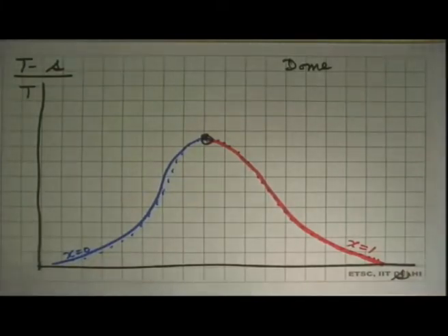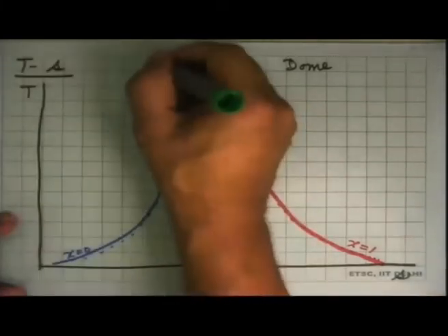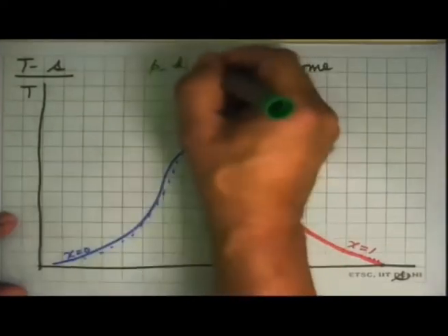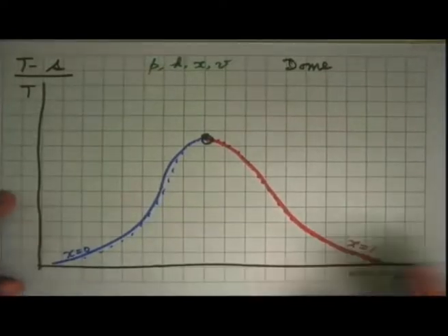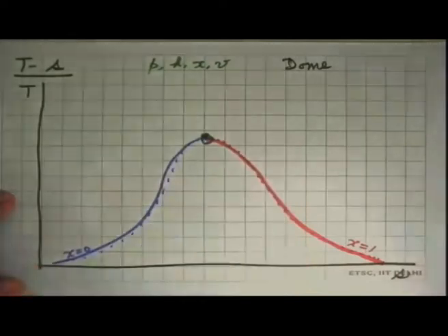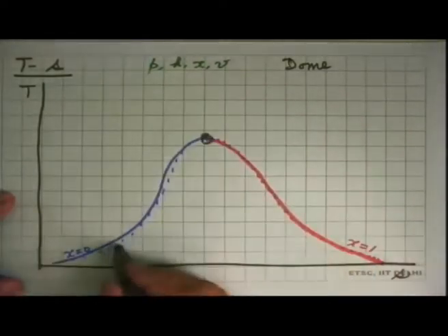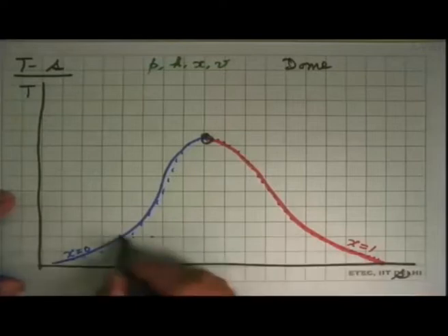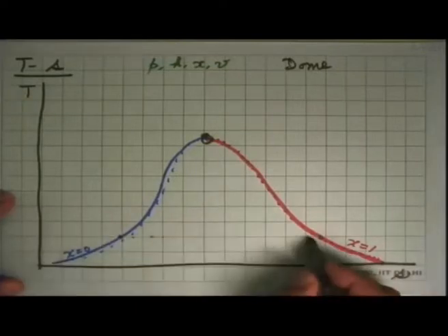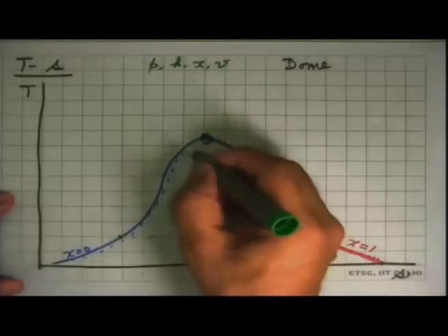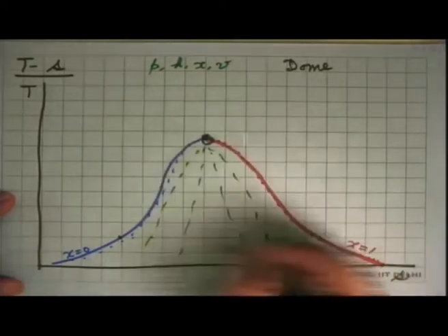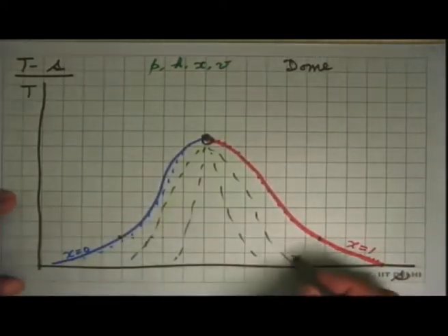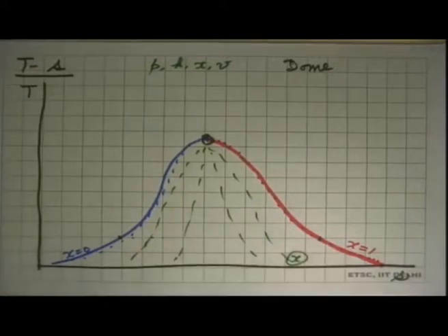And what happens here is we can now ask for constant pressure lines. We can ask for constant enthalpy lines, constant dryness fraction lines, and constant specific volume lines. Okay, so easiest one is x, and this will follow exactly the same style as we had earlier. At any given temperature, x equal to 0 is here, x equal to 1 is here, it is increasing monotonously here. Same with every pressure. So constant dryness fraction lines will all look like that. So these are constant dryness fractions, and they are always inside the dome.